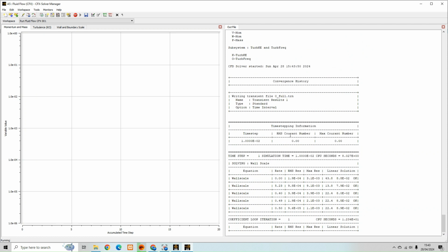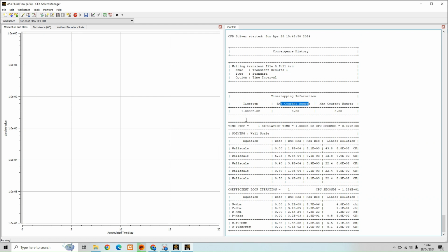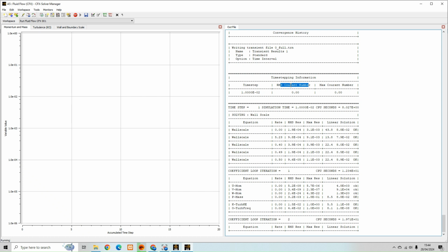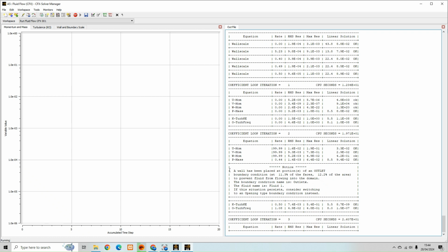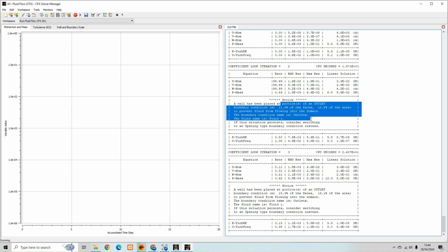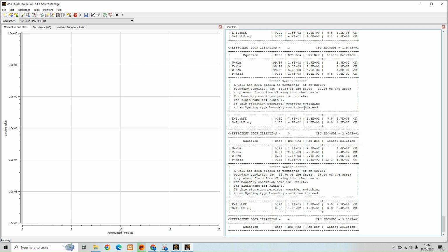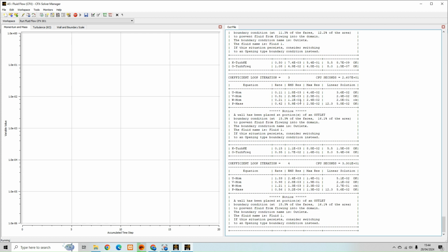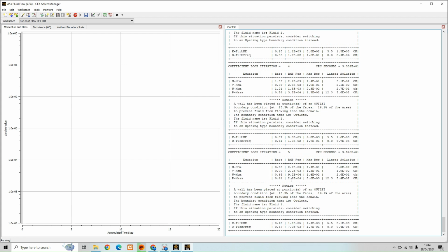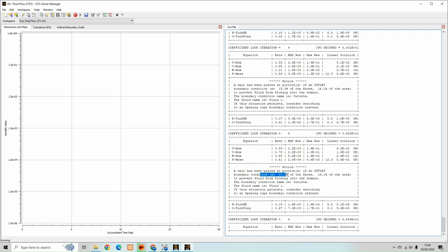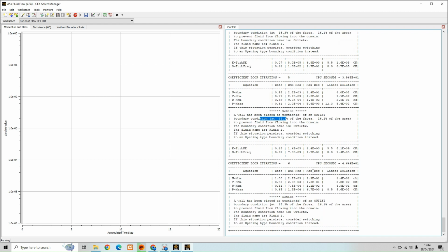So just a few things. In an ideal world, this RMS Courant number would be below 1. You're not going to see anything in the first time step, but when it comes up, you'll probably see it in the order of 10, maybe 20. What you'll also see initially at startup is this kind of warning. It basically says at the outlet, because it's experiencing some recirculation, it blocks the faces off. That will spike and then drop back down, hopefully. If it persists, worth just making the domain slightly larger, but yeah. You'll see something, maybe it's a 20%, and then it should just die away.